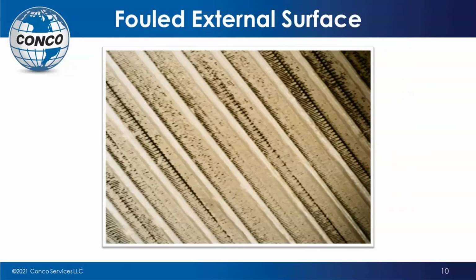And here's a picture of what one can look like when you let it go, or maybe you're just in a situation or an area where this is at the end of your season and this is what you're looking at. If you look at the upper right-hand corner of that picture, you can see that there's some air going through there. You can see the fins. You will get some air. It's going to be restricted some. You can see some of the fouling off on the corners, but you will get air through.